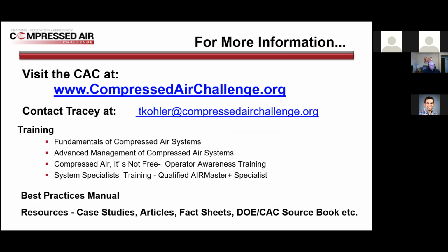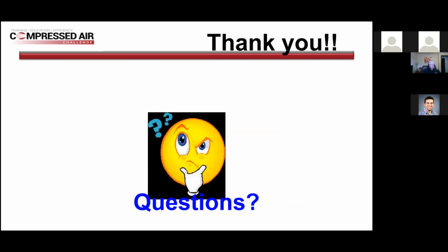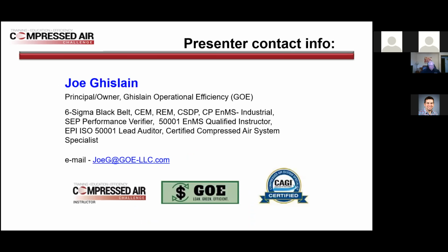Thank you for that. We have another question from Joe Junker from Oregon. What do you think about compressor VSD retrofits if not operated below 50% speed? I think that if it's not below 50%, you're going to lose some efficiency, again, because they're designed to do it at 90% of the full load capability. So you are going to lose some efficiency on it.